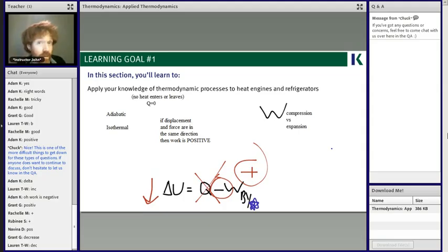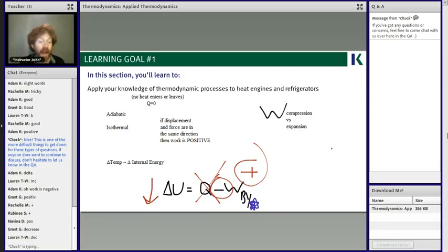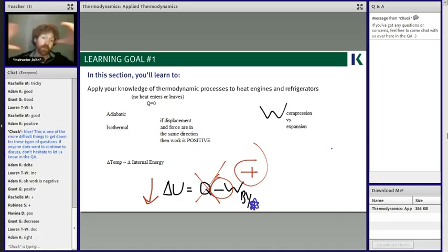Conversely, isothermal, and I know this is from the thermal one, so I'm just assuming it. Remember, you have a direct relationship. Any change in temperature is directly proportional to a change in internal energy. So that's just a major concept discussed in thermal 1. And so if you ever have a dramatic increase in volume, right, it's expanding out, temperature's got to drop. Conversely, if you compress it down really tight, temperature has to get very hot if it's adiabatic. Because if it's adiabatic, there's no heat going in or out, so you must change the temperature. Looking at the equation there, any change in U, there's only one thing you can affect, and that's the delta U, which is temperature.